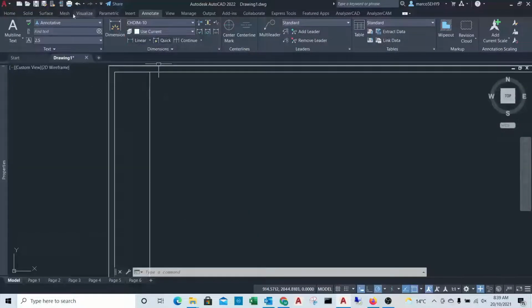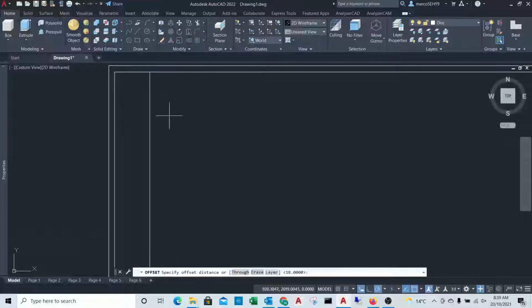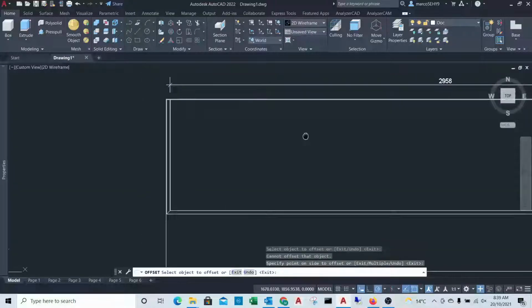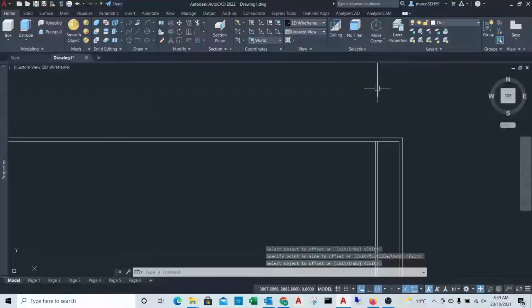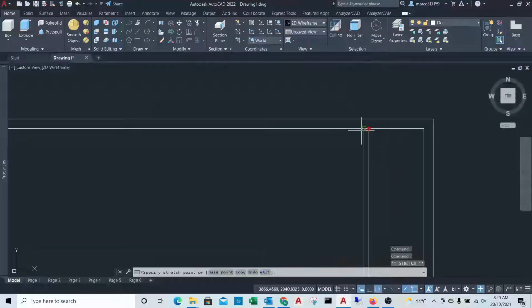I start the offset from here, 1.5 mm. This will be our tolerance gap. Now we can divide the cupboard into 5 equal cabinet openings. The 1.5 mm gap is a theoretical gap. Once the actual cabinets are manufactured and in place, you will not see it.